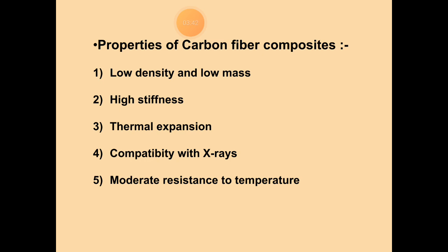Next one is high stiffness. Carbon fiber composites have high rigidity, manufactured using prepreg technology with standard fabrics. Also, for thermal expansion, carbon composites have a very low coefficient of thermal expansion: 4 times lower than titanium, 5.5 times lower than steel, 8.5 times lower than stainless steel, and 11.5 times lower than aluminum.